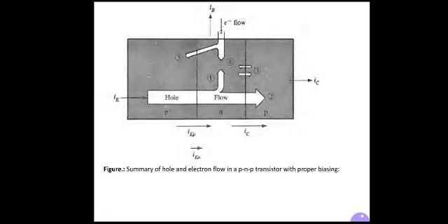There must be some base current due to the requirement of electron flow into the N-type base region. So we account for IB physically by three dominant mechanisms. The first one is that there must be some recombination of injected holes with electrons in the base, even with WB much less than LP. The electrons lost to recombination must be resupplied through the base contact.